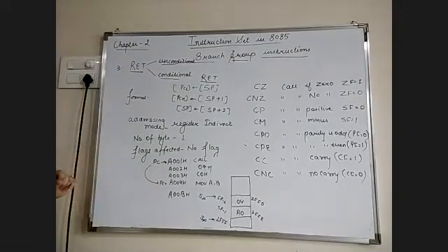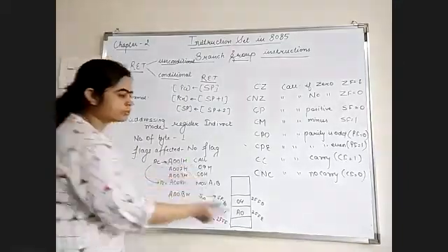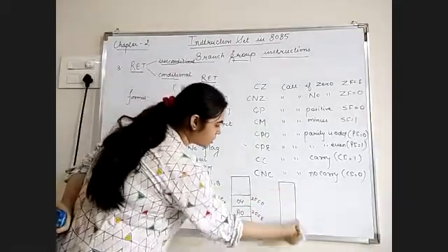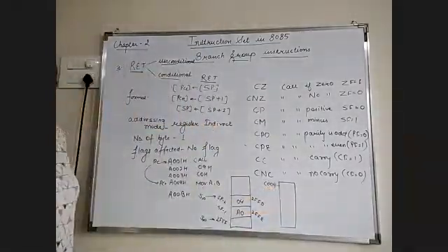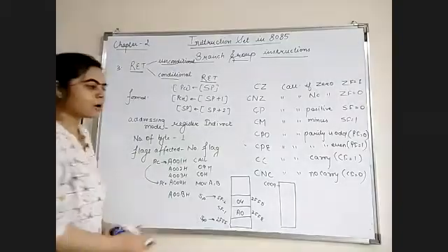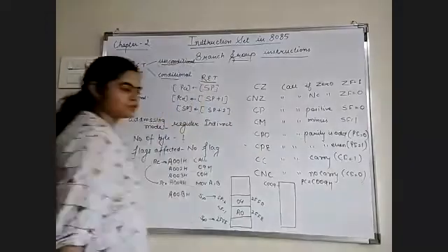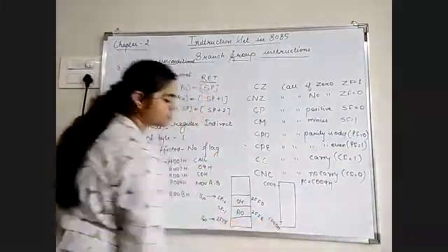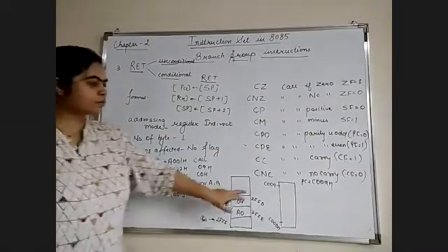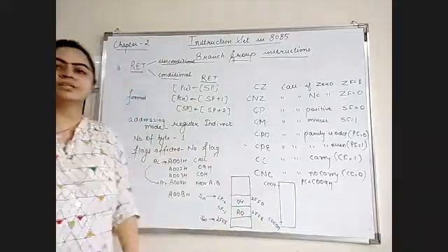Once the pushing is done, the microprocessor will jump to the memory location whose address is C009H. Here we have a subroutine program that starts from memory location C009H, so the program counter is updated with the address C009H. The subroutine program starts from C009 and goes up to C00D.